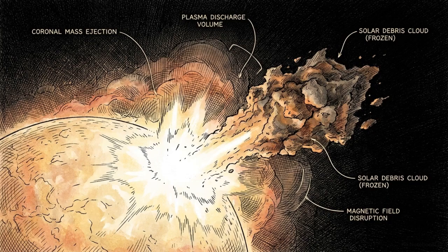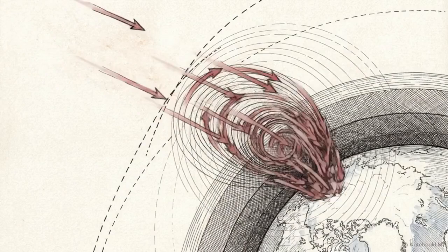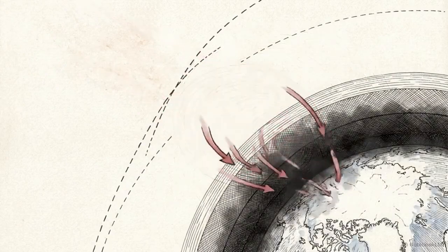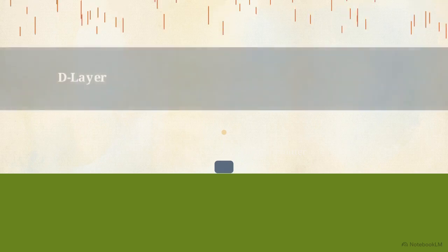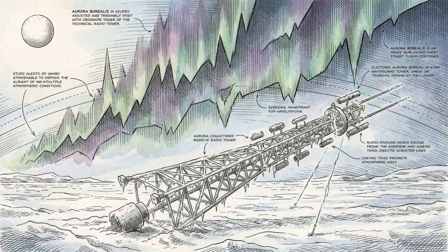High-latitude circuits also face the threat of polar cap absorption, triggered by solar proton events. During solar eruptions, high-energy protons are funneled toward the Earth and guided by magnetic field lines directly into the polar atmosphere. These protons strike the low-altitude D layer, causing a massive, sudden increase in ionization. This turns the layer into an impenetrable absorber that can completely block radio signals for several days. Closing polar radio links requires signals to survive space weather events that are concentrated and guided by the Earth's magnetic geometry.